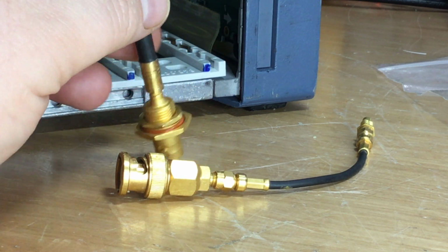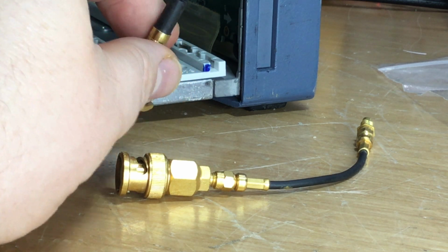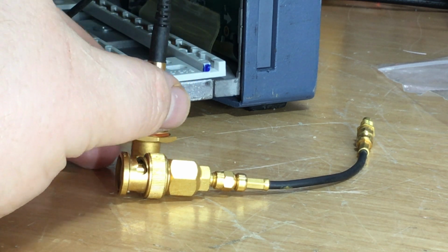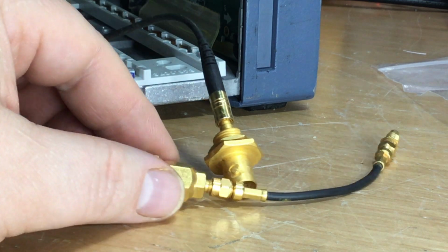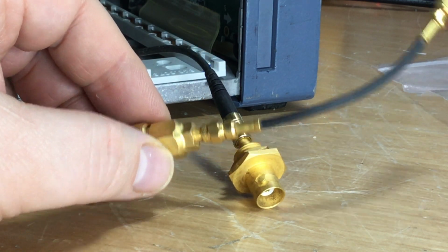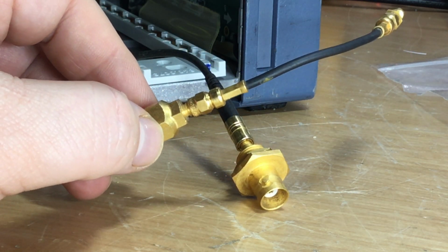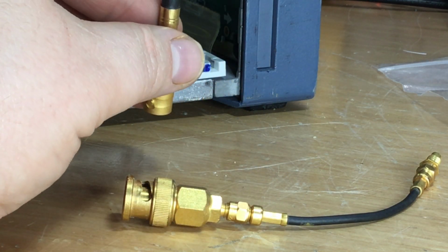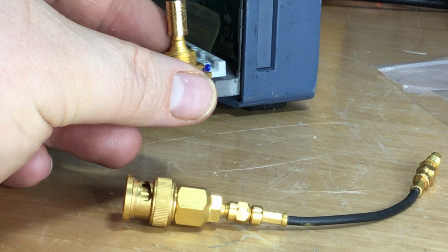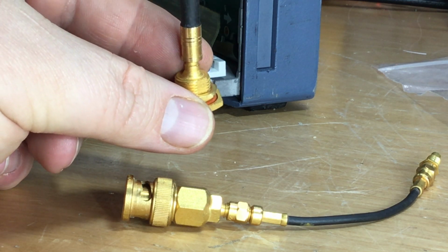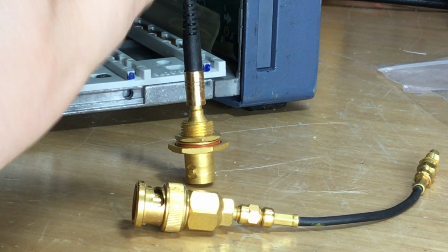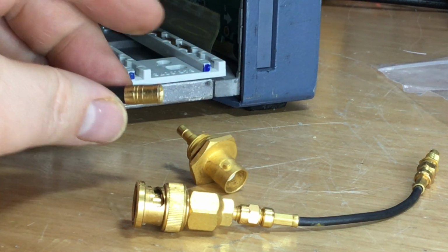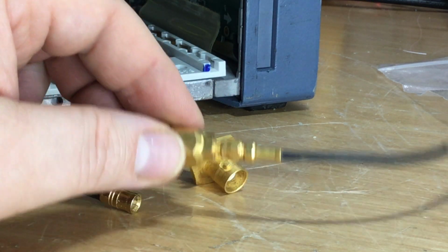So you tend to find in aerospace things like satellites, defence electronics equipment, all those kind of things tend to have SMCs on them, whereas non-vibration environmental pieces of equipment tend to have SMBs on, because the push fit is adequate for that particular application.